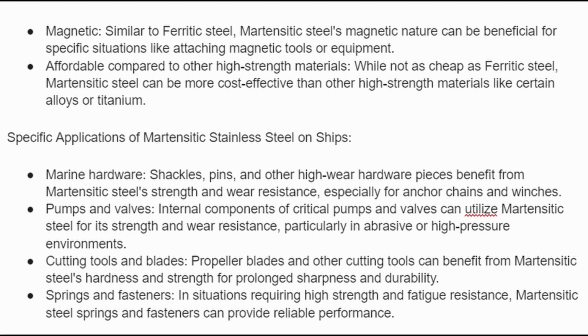Marine hardware, such as shackles, pins, and other high-wear hardware pieces, benefit from martensitic steel's strength and wear resistance, especially for anchor chains and winches. Pumps and valves. Internal components of critical pumps and valves can use martensitic steel for its strength and wear resistance, particularly in abrasive or high-pressure environments. Cutting tools and blades. Propeller blades and other cutting tools can benefit from martensitic steel's hardness and strength for prolonged sharpness and durability. Springs and fasteners. In situations requiring high strength and fatigue resistance, martensitic steel springs and fasteners can provide reliable performance.